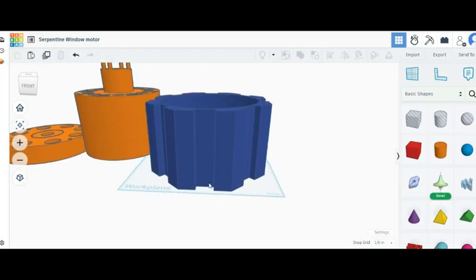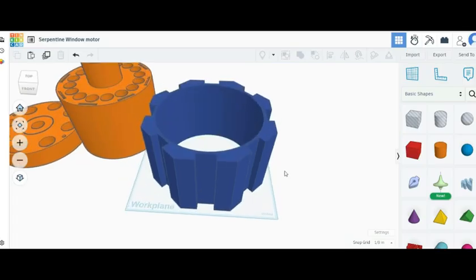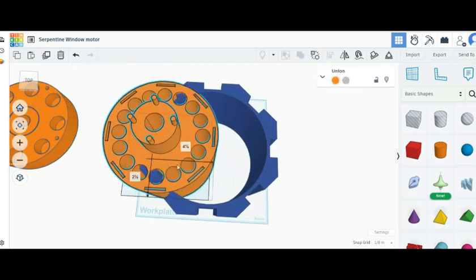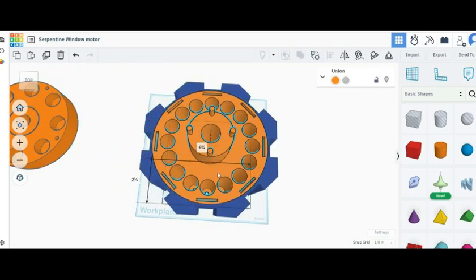So you'll take your first wind, you'll go up, up, up there, over, down, down, down there, over, up, down. Then you get right back to the start. Now there's a little bit of wire there, so you're a little bit further here, and then there, until you've put one layer here, and then just put multiple layers. This is, I think, I don't know, like 1/4 inch. I might make it more like a 1/2 inch. I think eventually you're going to be too far out from the magnets. But that's the idea. And then once it's done, you slide it right in there, like that.